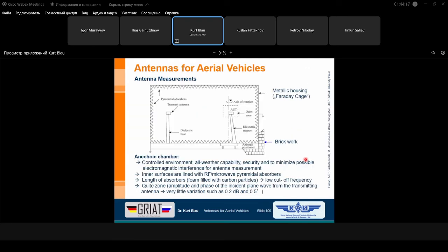And here you can see a very large building or measurement room. It's not a compact range. You know, the compact range has the advantage, as also coming from the name, that we can reduce the distance between the antenna under test and the illumination antenna, but the disadvantage is the magnitude error across the measurement plane.